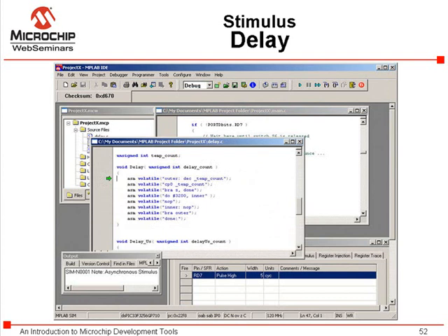Delay routines such as this are often used to slow things down, so that a display can be seen by the human eye, for instance. When simulating, which runs at a slower speed than the actual processor, these delays are often not needed. While using the simulator, we just need to know that the delay routine is called, but we don't want to step through thousands of iterations of a delay loop.